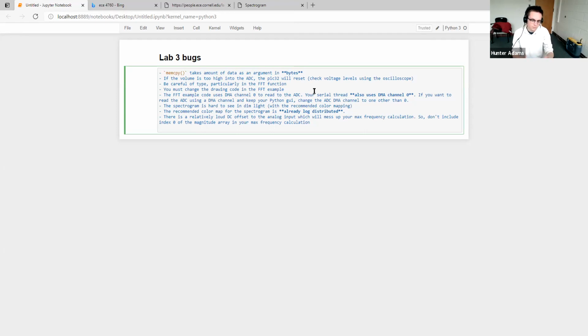Something else. Some other tips that might help you with debugging. If you are doing high-speed prints, which generally speaking isn't a great idea, but if you are doing them to help with your debugging, we have found those can crash the Python interface. But if you open a PuTTY connection to your PIC32, that PuTTY connection is quite stable for higher speed printing.